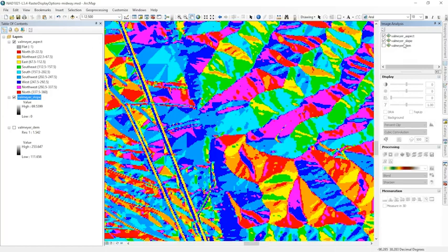So if I select my Valmeyer aspect raster, I can select the brightness and contrast and things like that I can select in the raster properties pane. I can also select the color ramp and then use a powerful tool that we're not going to go through here called raster functions. These are also in ArcGIS Pro, and while I want to cover them, they're a little advanced for us right now. But if you're interested in running custom functions that manipulate your rasters directly in the display view, check those out. For now, let's focus on the swipe tool.